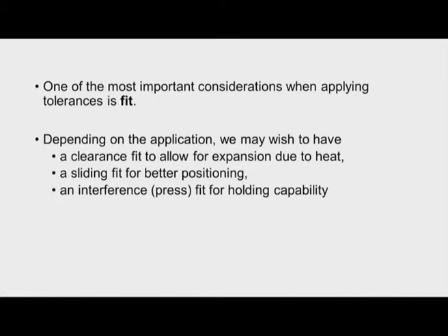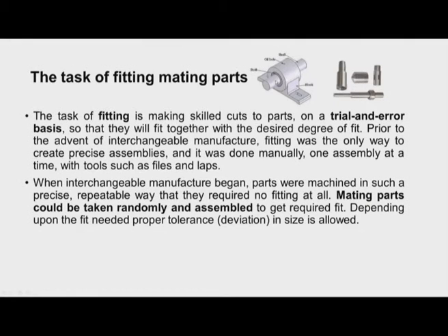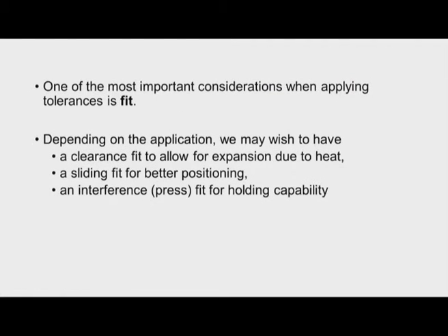Now one of the most important considerations when applying tolerance is the fit. What is the kind of fit? I gave the example of the bush, shaft and the body. Between body and bush no movement is required, so there a tight fit is required, whereas between the shaft and bush some clearance is required so that the shaft moves easily. So a clearance fit is required.